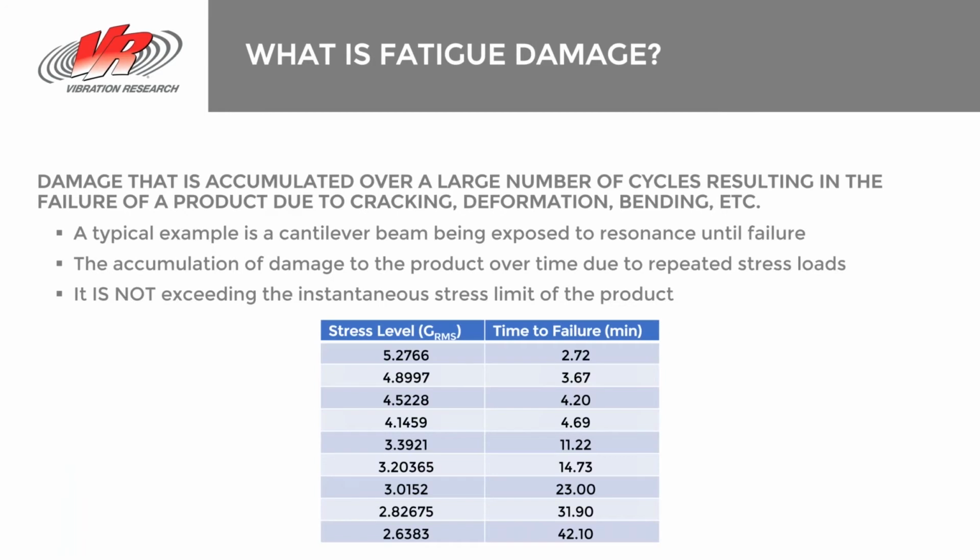So the first question that I asked was, what is fatigue damage spectrum? And this mentality is something that you have to wrap your head around. We're not trying to replicate an instantaneous shock or the shattering of glass. The fatigue damage failures that are being replicated through this type of testing are high cycle fatigue tests.